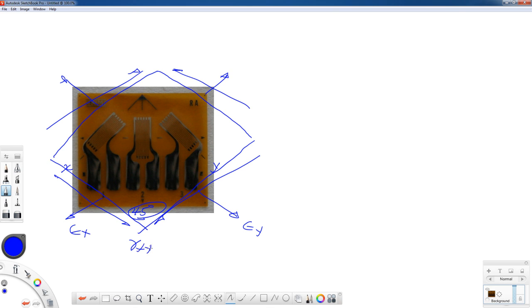Now, in some cases, the strains change very quickly over a small area, so you would have to use very small strain gauges. I put on some extremely small strain gauges myself. They're kind of hard to see, they're kind of hard to solder. If your strains don't change very much, then you can get by with a very large strain gauge that's a lot easier to work with. Let me show a picture of some strain gauges. One of my students and I put on a specimen.